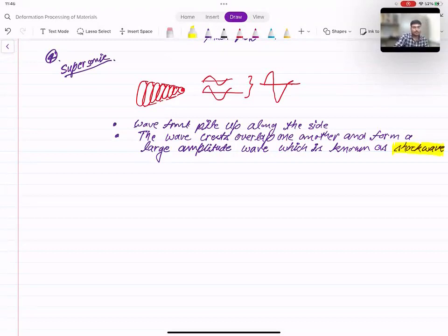Okay. And here the Mach number will be obviously greater than 1, because the speed of the object is much higher than that of the sound. So Mach number is greater than 1. Okay. So this falls in the supersonic range. Okay. Now, based on this concept, let us see an interesting fact: when the space shuttle re-enters the atmosphere from space, it has a Mach number of 25. So that is extremely high. Okay. So that's why when the speed is that much higher, the materials out of which the space shuttle is made should have very high thermal stability. Okay. So let us put this as a note here.